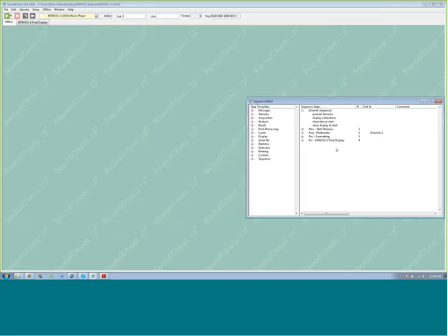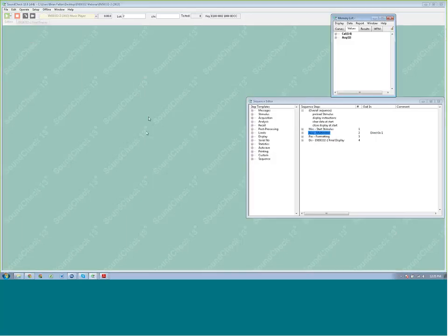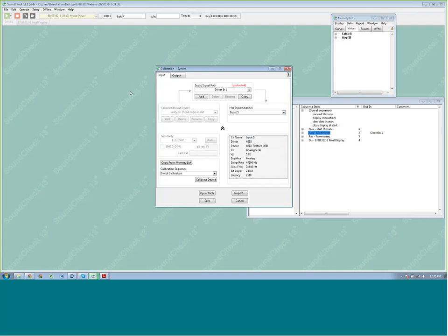Now, this sequence is pretty straightforward. It's rather small, and we only have one input. So we're just monitoring the level coming back from the phone in this case, and we're measuring it through the signal path direct in 1. As far as calibration goes, there really isn't any. The only step you need to do is go to direct in 1 here on the signal path and make sure you have it set to the appropriate hardware channel. So I have my device plugged into input 5 on my RME card right now.